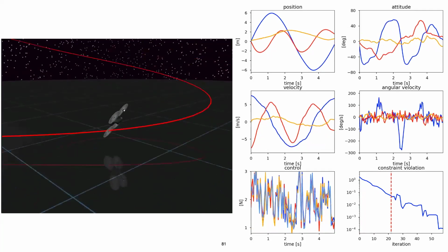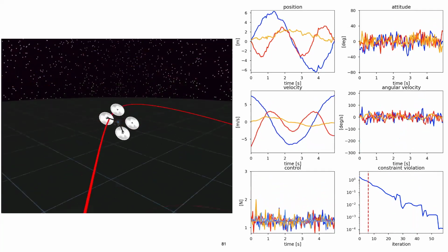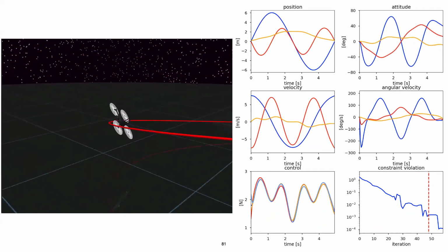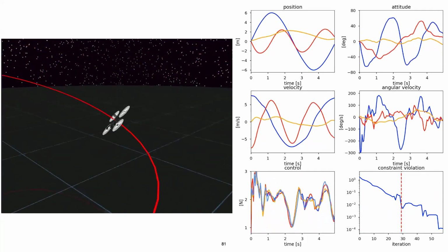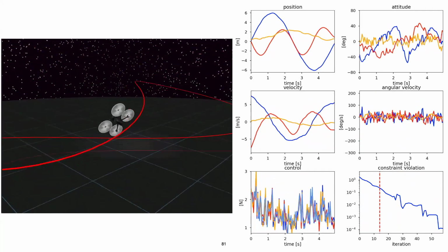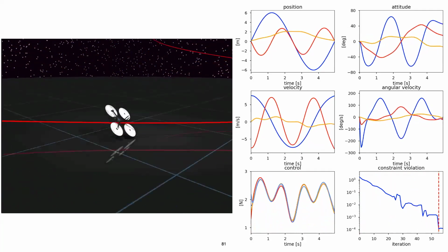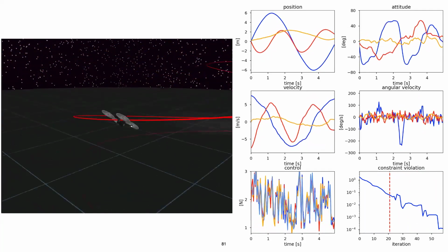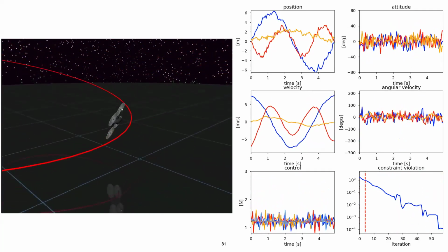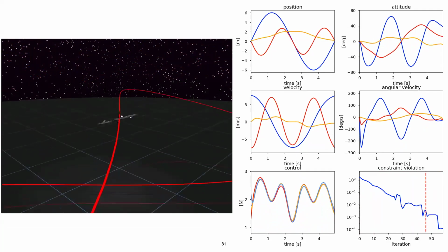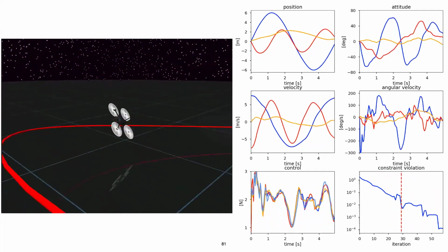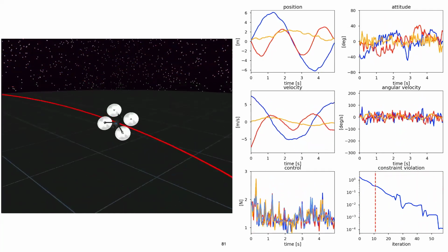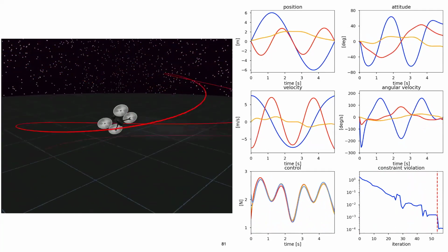And then it's just nice in general looking at how we initialize these variables and what they actually converge to. So for instance, for our control, we initialize with just noise about hover. It's noise about hover for a little bit, and then it gets a little noisier, and then it converges on this beautiful, smooth, optimal trajectory. And what's nice about this is that everything here is entirely no derivative, no models used in the sense of no A's and B's. And we're able to recover this beautiful optimal control looking performance.